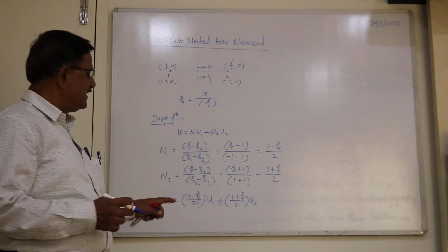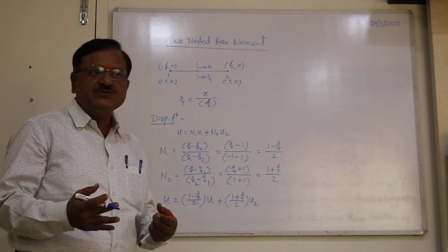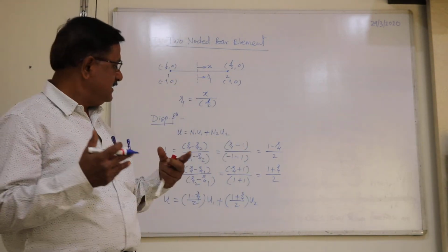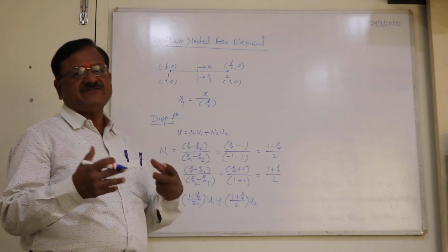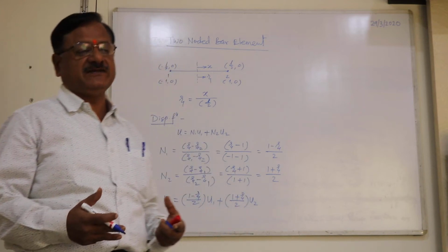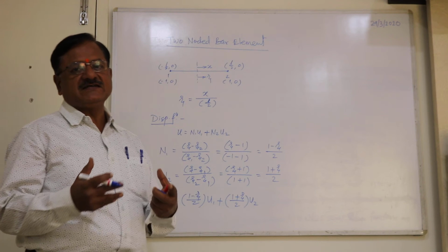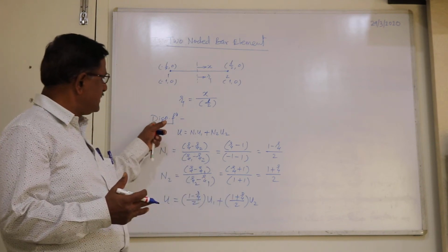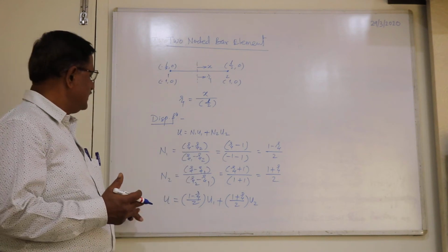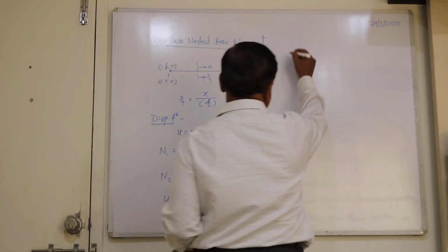So therefore we have to express the geometric function in terms of the same shape functions. Such an element, in which the same shape functions are used to describe the displacement function and the geometric function, is said to be an isoparametric element.